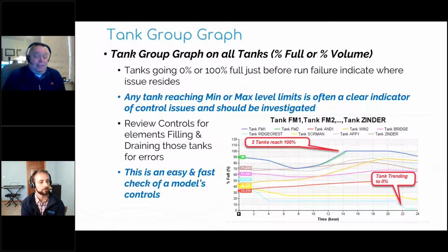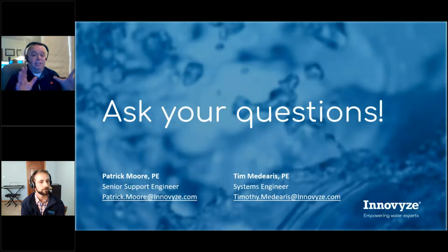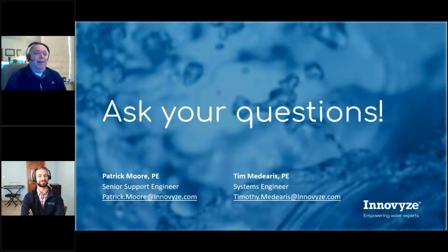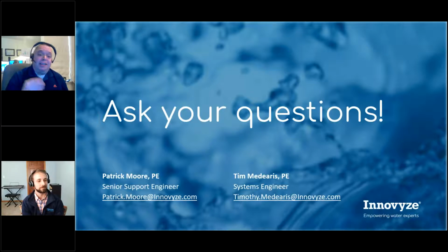Usually that helps you solve it, and that's pretty much the vast majority of things that people run into if their model's not running. If you know these, that's probably 80 to 90% of the time going to help you solve it because you now know where to look. Full hydraulic status report, generate warning messages, look there, use this, download that little PDF that we put on there. If you still need help, feel free to contact us, but knowing these things really helps you solve most things you'll generally run into. And I think that helps so much.